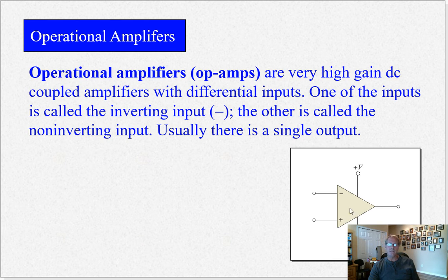And what we'll see is these operational amplifiers in open loop mode, in other words, no parts around them, have gains much higher than 2, more likely 200,000, which is impractical. You can't get 200,000 volts out here unless you have a 200,000 volt power supply, and if you have that, you better be careful because you're going to get hurt. So don't do that. But we'll see that when we add negative feedback to this circuit next week,